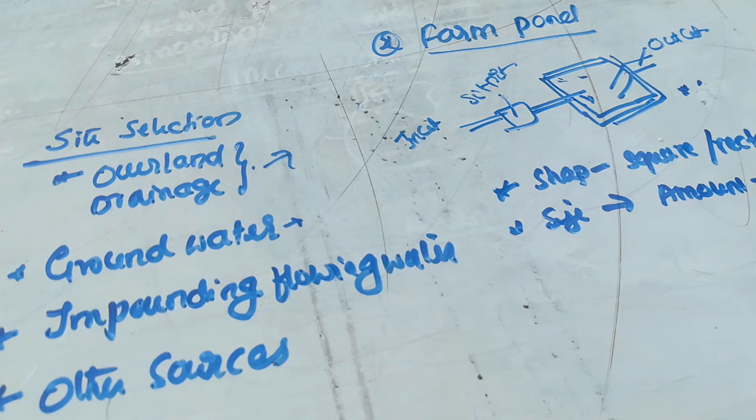And depth and side slopes of farm ponds, that is also important. The depth of the pond is generally determined by soil depth, kind of material excavated and type of equipment used. The selected pond depth should be equal to or greater than the minimum required for the specific location, as depth of pond is the most important among the three dimensions. In semi-arid regions, the evaporation losses can be reduced by deepening the pond for the same volume of water stored, as the area occupied by the pond is lesser.